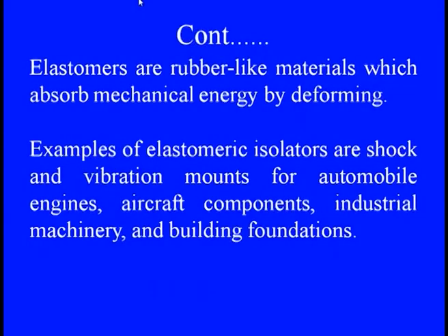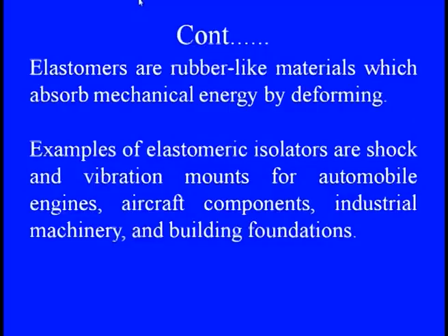So, elastomers, when we are talking about them, these are always a damped feature in which rubber-like materials are there, through which we can absorb the mechanical energy under the force due to the deformation. So, elastomeric isolators are used in vehicles, where they are always used to absorb the shock vibration or the cyclic vibrations.